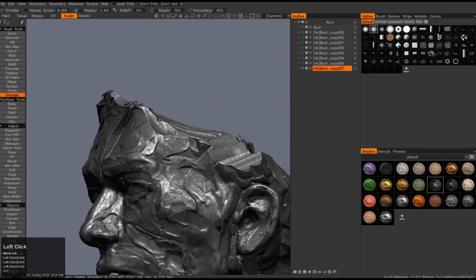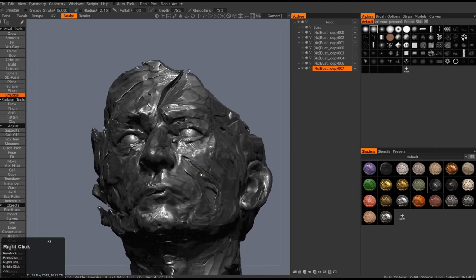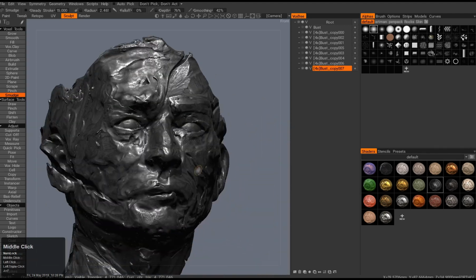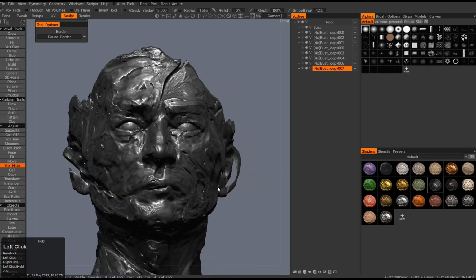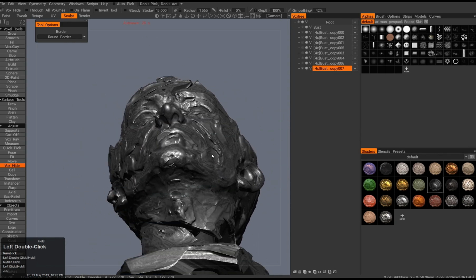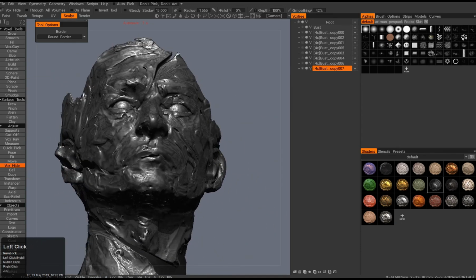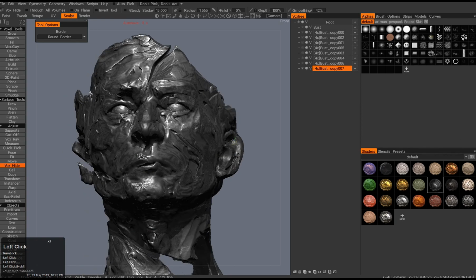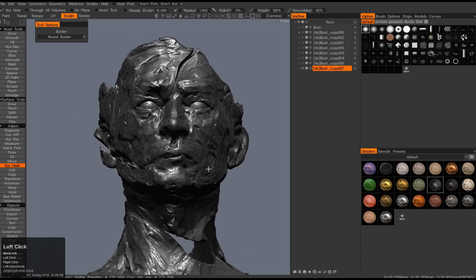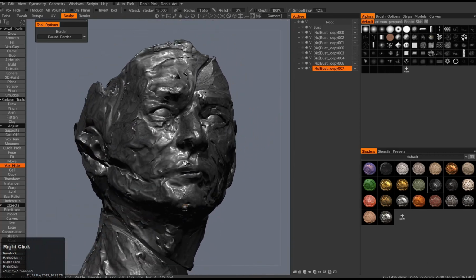Because sometimes what happens is that you press the delete voxels button and you no longer can unhide anything, but if you change the resolution of the model and go up by like 1 million triangles, it will unhide everything. So in that way, when I duplicate it, I always know that it's been a clean duplicate and nothing has been hidden.